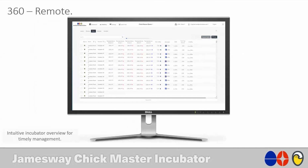This is a slightly different view of that exact same data. And this view, what we've seen from customers, is a great way to spot outliers on your incubators. So if you're finding an incubator that's behaving a little bit differently, this overview of how your incubators are configured will tell you straight away if the damper, for instance, is configured in a manual mode instead of a humidity mode in terms of control. Equally, you can see from here your stage profile breakdown on the machine.